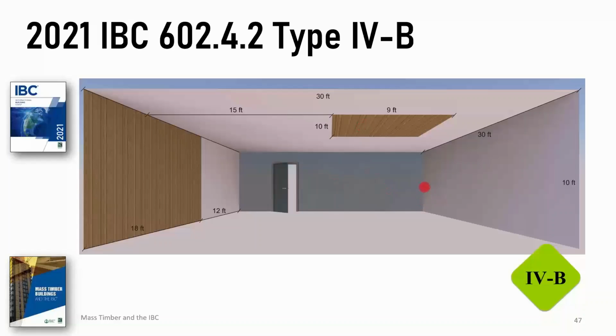What's the concern here? Well, in a fire scenario, if the sprinklers don't put it out or the sprinklers don't go off, you don't want the contents fire. This will obviously begin to burn, char, and may reflect off each other. We don't want them reflecting off each other. This will enable, when the contents are burned out, the combustion of the mass timber to be unsupported. It will put itself out.